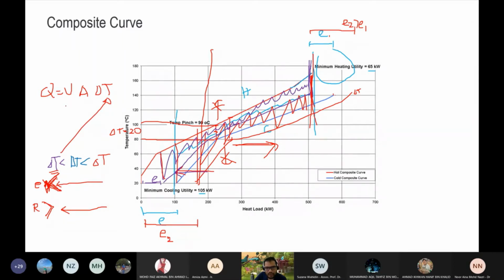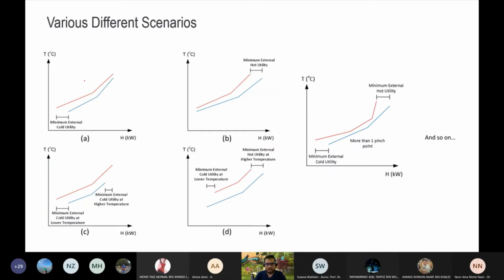So to recover the same amount of energy, we will have to have a much larger area of the exchanger. So it means a larger heat exchanger. So see if you have some space on the field. If you don't, then we are limited to that space. So this is what I've been talking about.